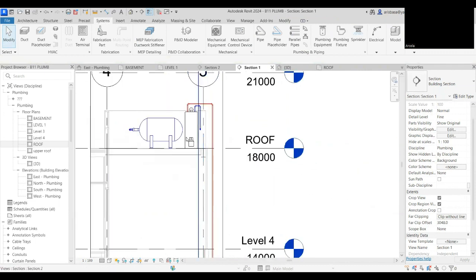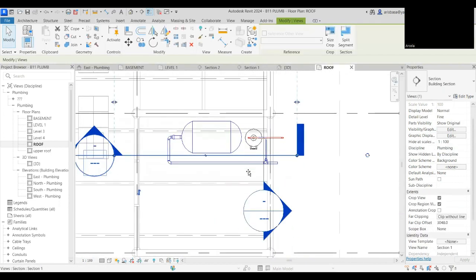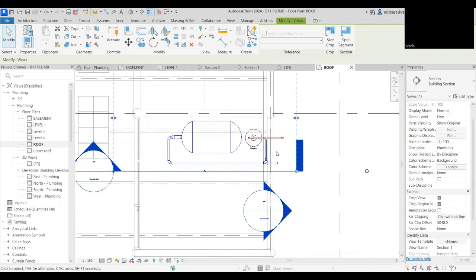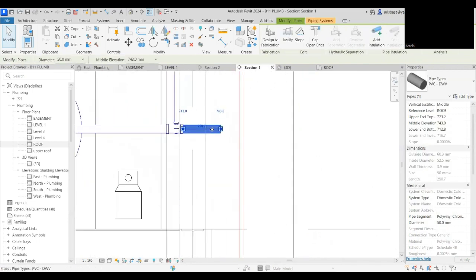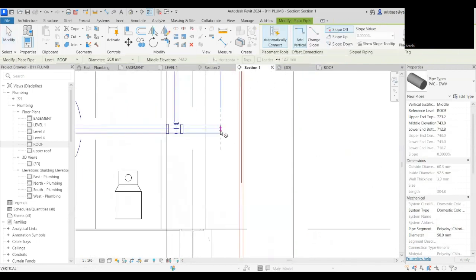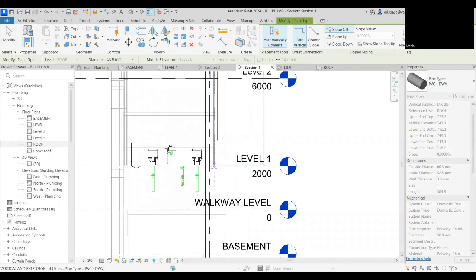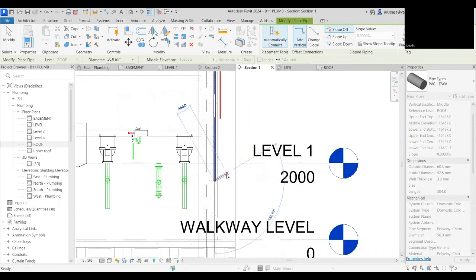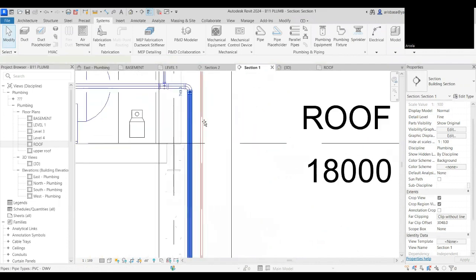So this is where's the other pipe? We need to move the section view again. So let's move this section view here so that we can add the pipe for the cold water pipe going down. Go to the view. This pipe, create similar. Get this to go down up to this level. Okay. We can move it out of the wall, no worries. It will adjust.